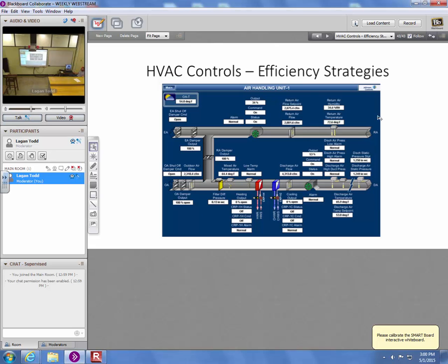Yeah, and we do still see a lot of the early digital control systems, and even a lot of them up until fairly recently didn't come with the graphics package. So that's all you would get is tables. Yeah, and then you got to go. Right, and then it's, if they wired it right. Yeah, that's my job, to go through and test it all after it's installed and make sure that they did wire it right. Now when you add graphics, you have the potential to accidentally pull the wrong point value into this field. So you might swap these two. When I look at this, I think that you're commanding the heating valve open and the cooling valve closed, but it's actually the opposite, right? So it's got to flush out all those little errors. That's one of the first steps in my job in these projects.